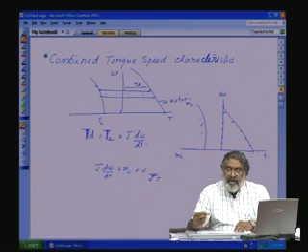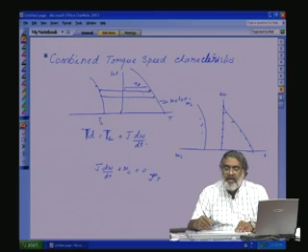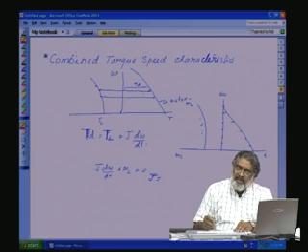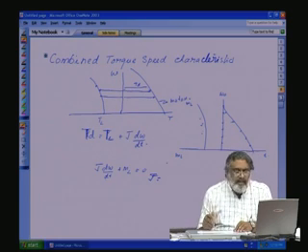The driving torque is required not only in steady state; during acceleration and deceleration also we have to give transient power to the system. That transient power depends on the moment of inertia of the system, and a typical system for finding the moment of inertia was also explained.